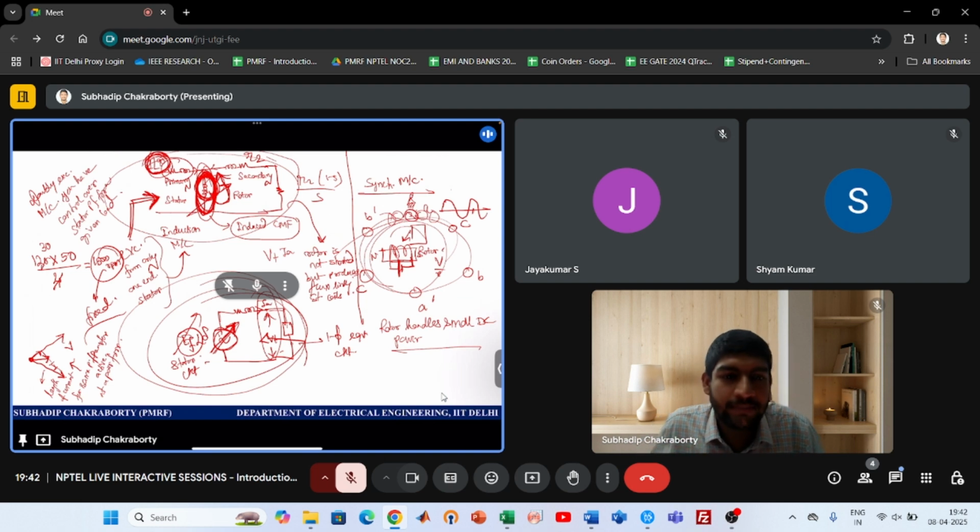And locally, you try to improve the power factor, because from that frame of reference, you are actually trying to push the power or enhance the power transfer capability with minimum losses, or with minimum length of current, which enhances the power transfer capability. You can push more power, right? If for 100 watts the current required is only 2 ampere, I can push more power, right? I can generate more power because the conductors will not be burdened, right? So that is the whole concept.